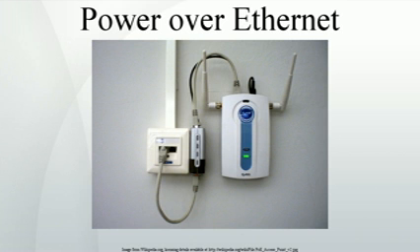Devices needing 5 volts cannot use PoE at 5V on Ethernet cable beyond about 15 feet, 4.6 m, due to IR loss, so a 24V or 48V to 5V DC-DC converter is required at the remote end. Passive DC to DC injectors also exist which convert a 9V to 36V DC input power source to a stabilized 24V 1A or 48V 0.5A PoE feed with plus on pins 4 and 5 and minus on pins 7 and 8. These DC to DC PoE injectors are used in various telecom applications.